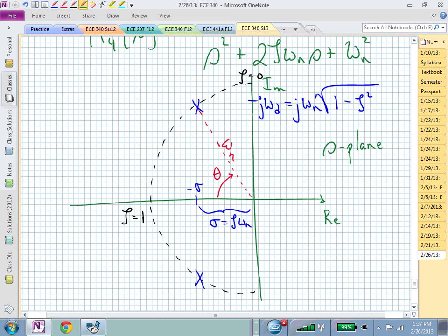You're doing an approximation, but you're getting something that in the limits is behaving like what the real system will do. We are going to go ahead and let zeta be 1. We'll just slide these two so that we now get 2 real roots instead of 2 complex conjugate roots. And then we'll just sketch real roots, and we'll have 2 real factors to sketch instead of having to worry about 1 complex pole pair or 1 complex zero pair. Is that clear? Yes.